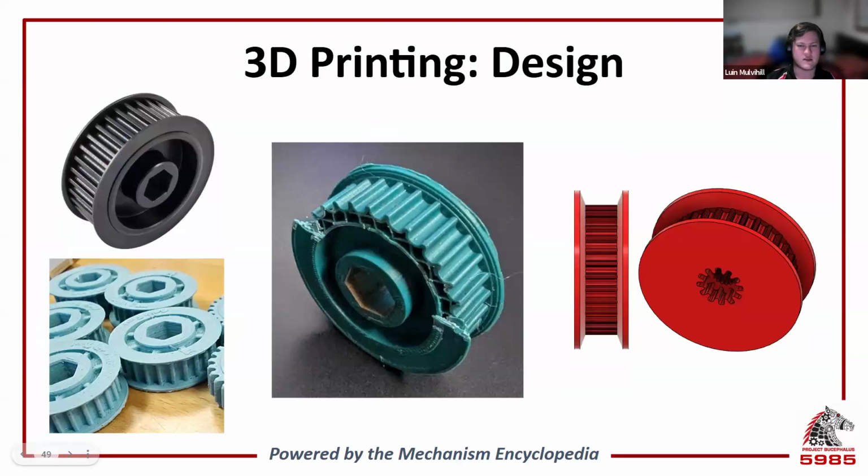We'll come back to gears later because there's a lot to discuss, but for now we'll talk about pulleys. So when printing pulleys, you might be tempted to download the step file of a COTS part and just print that. But the design for the metal COTS pulleys has a very thin flange that's prone to breaking, and it also has a cavity which creates overhangs, making it harder and slower to print. There can sometimes be text in the model as well, which also unnecessarily increases your print time.